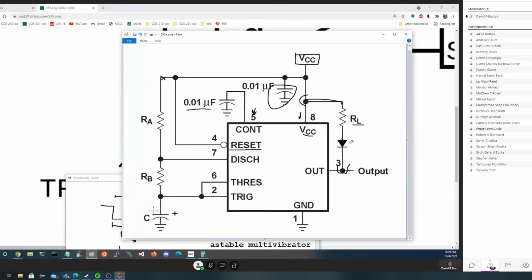Okay, that sounds good. We know capacitors have a charge and a discharge time associated with them. We may be getting somewhere if we can control how fast this takes to charge or discharge. Now, let's move ahead. We have the discharge value hooked to the top of resistor B, and we know we can open and close that by manipulating that set reset value we have in there. So the latch can let us turn this on or turn this off.